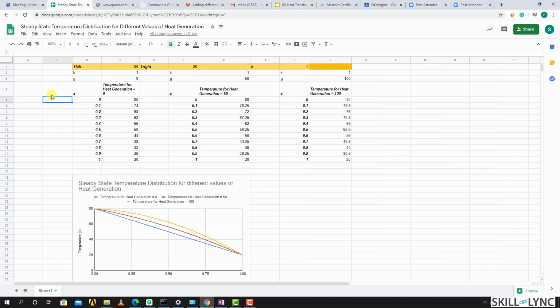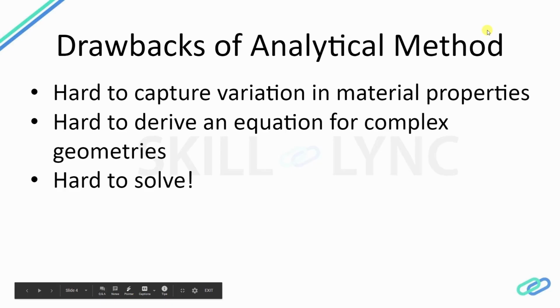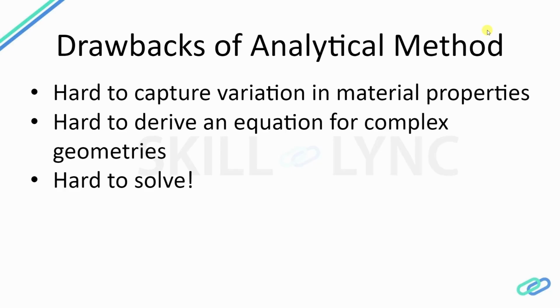Now, yes, your accuracy would be much better if you derived the governing equation using cylindrical coordinates, because most of your cells are cylindrical in shape. But if you see a cell that's rectangular in shape, then this approximation would be okay. But the one-dimensional assumption would no longer work. You would have to at least use a two-dimensional temperature equation. But the derivation process for the 2D equation is exactly the same as the derivation process for the 1D equation. Alright, now that being said, let's discuss the drawbacks of the analytical method.